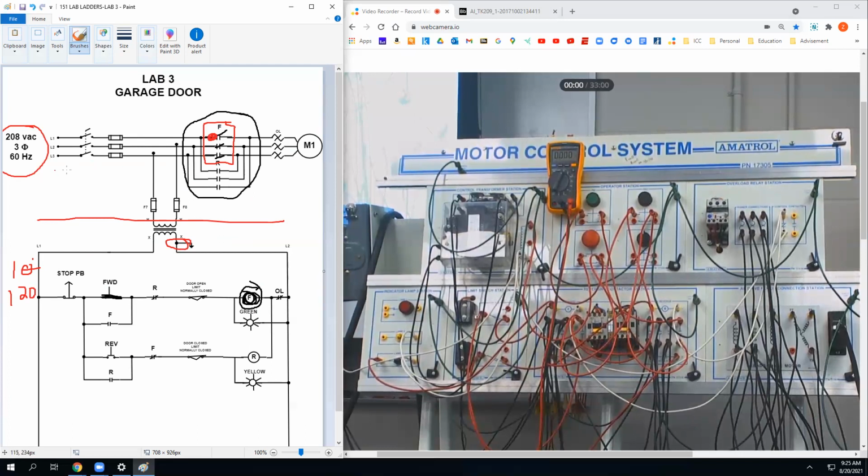And it's not even shown on this print, but do you remember how I showed you guys the little neutral on the front of the disconnect? In front of the disconnect, you got L1, L2, L3, and then it says N, neutral. I told you guys we need to take that and reference it to ground, right? So this is going to be your best reference for potential for your negative lead in the power circuit.